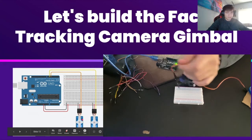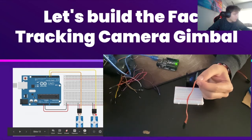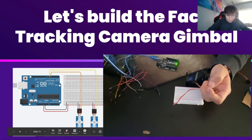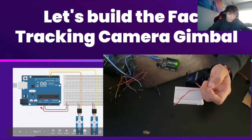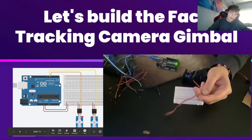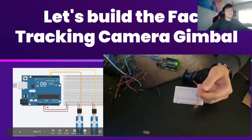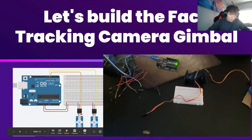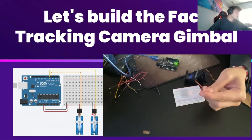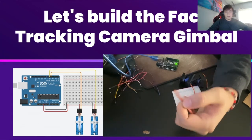If you look at the servo, it has an orange, red, and a brown wire. As you can see, the red ones are the ones in the middle. Those go to the 5-volt from the Arduino, and then you're going to connect the brown wires to the ground that's connected to the Arduino as well. Those grounds are connected to the brown wire of the servos, so that's going to be the far left if you're looking at it in this orientation.